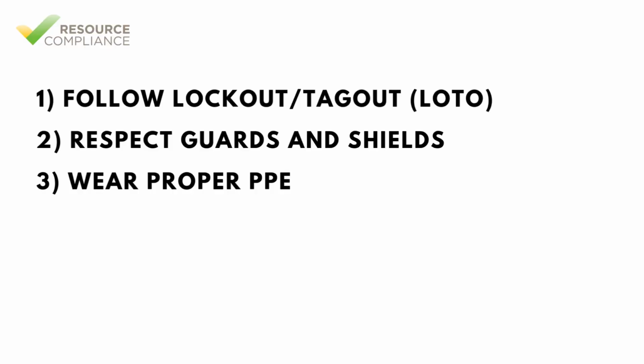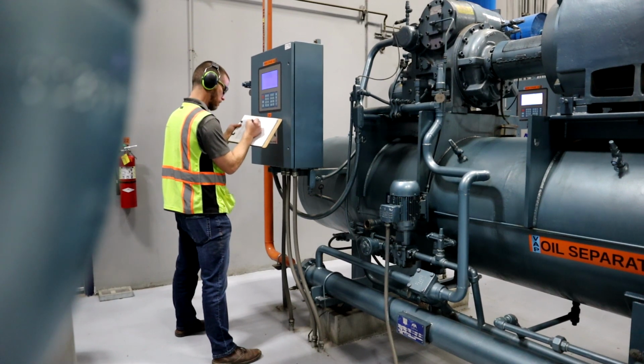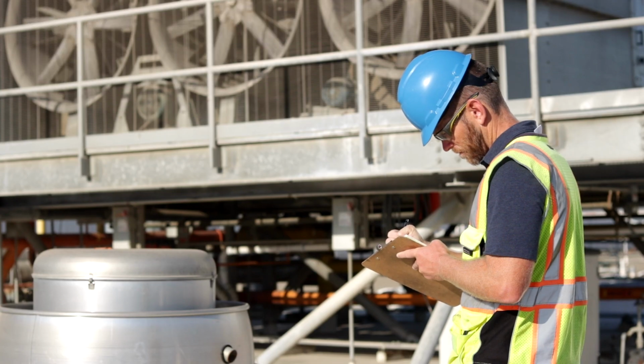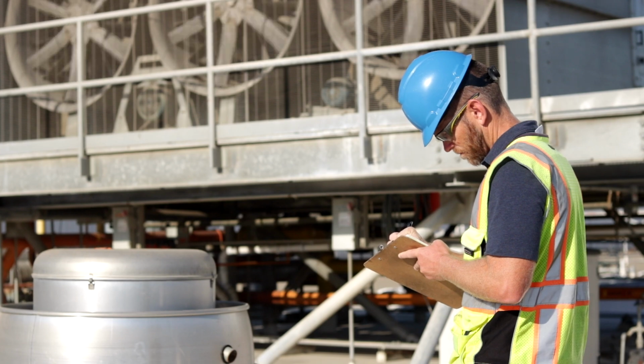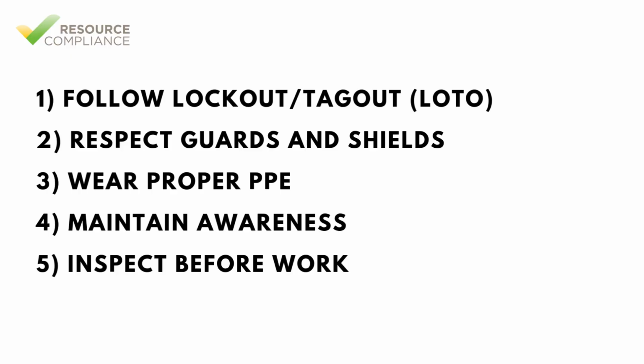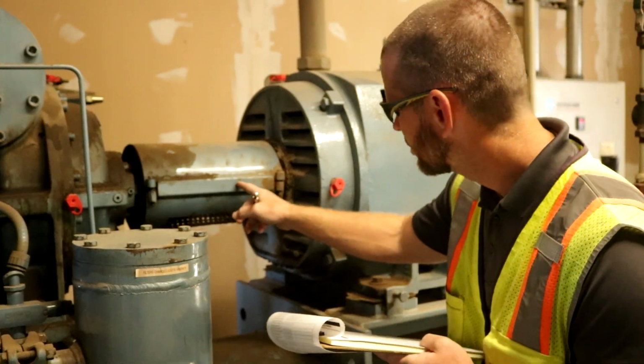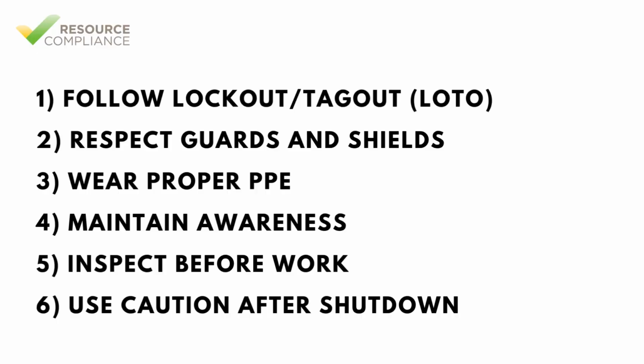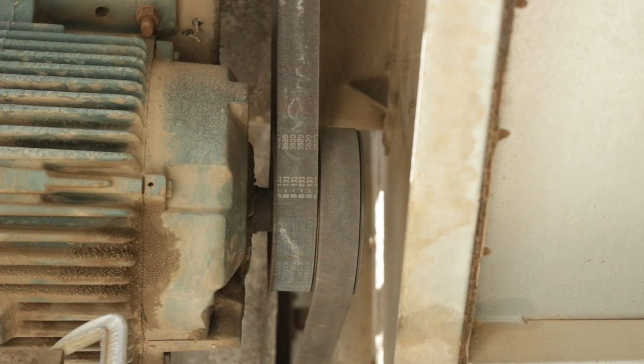Safety glasses, hearing protection, and snug-fitting clothing are critical when working near rotating machinery. Stay clear of rotating shafts, couplings, belts, and fans when equipment is running. Verify guards are in place, fasteners are tight, and components show no signs of wear or damage before starting equipment. Wait until all motion has stopped before approaching machinery. Flywheels, fans, and motors may take time to wind down.